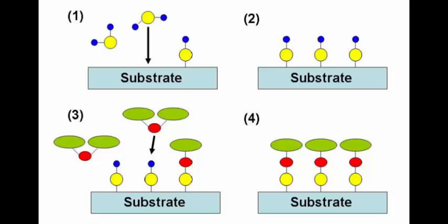One of the fundamental differences between ALD and other deposition techniques is the way in which the reactants are exposed to the substrate. In ALD, the reactants A and B are individually exposed to the surface, allowing for a sequential layering process to occur.